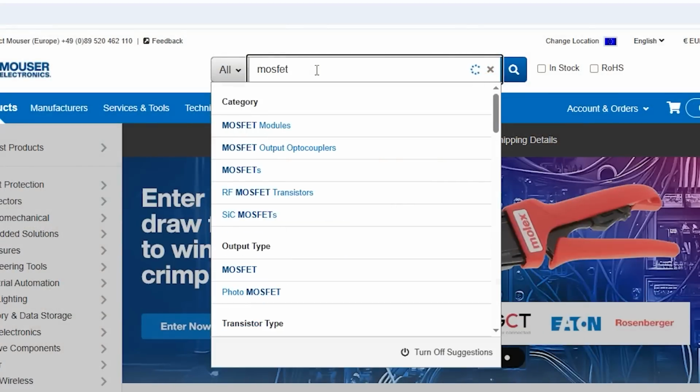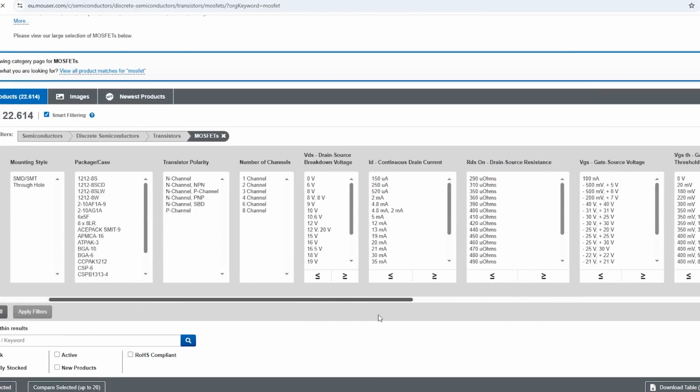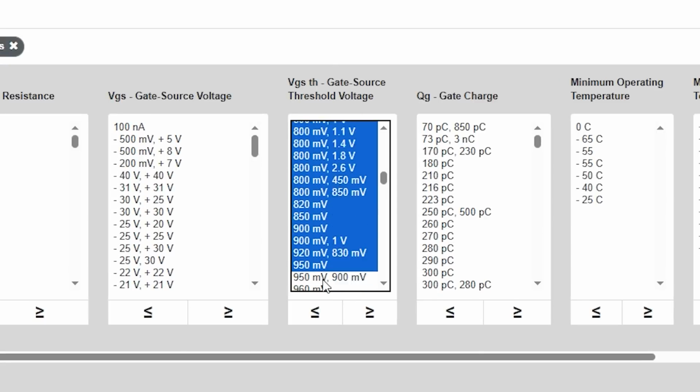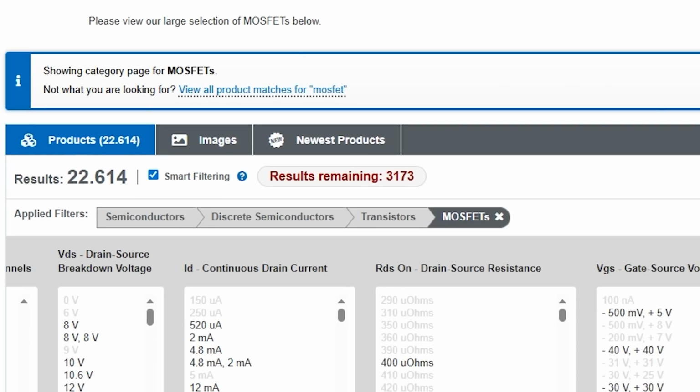By doing a simple search on online part seller websites like Mouser, you can see that the number of MOSFETs with a gate-source threshold lower than 1 volt is something around 7%. This means that you will be limited if you want to use a MOSFET in a circuit operating on 1.5 volts, while almost all BJTs are fine with 1.5 volts.